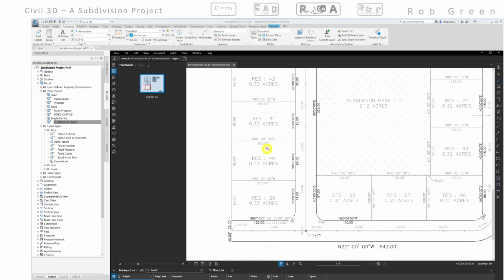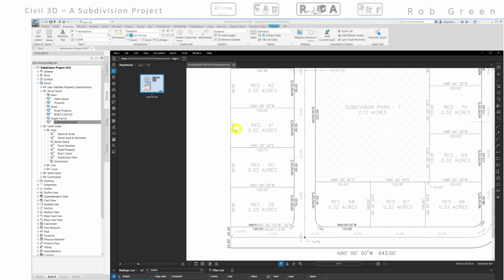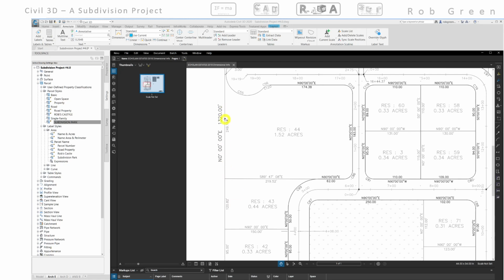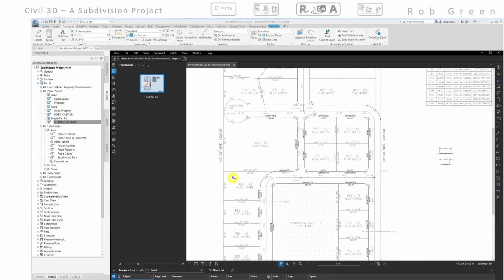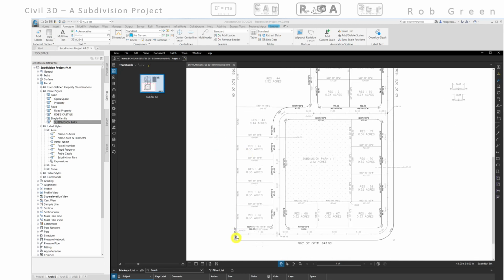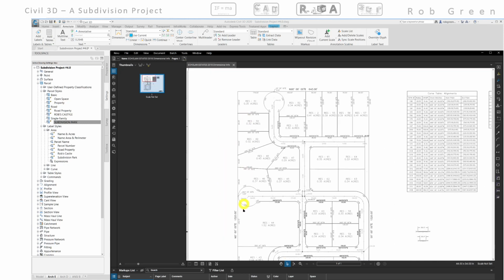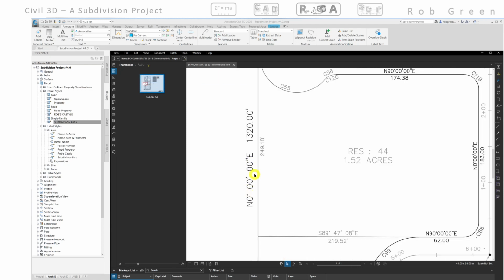So let's notice that on this wall we can see that there is no bearing over the distance. It's just a distance. So why is that? That's because there's one main label up here that's above the line that is larger, which is indicating that all the way from the previous label above the line, so from this point here up to the end of this straight line, which is here, is all at this particular angle.